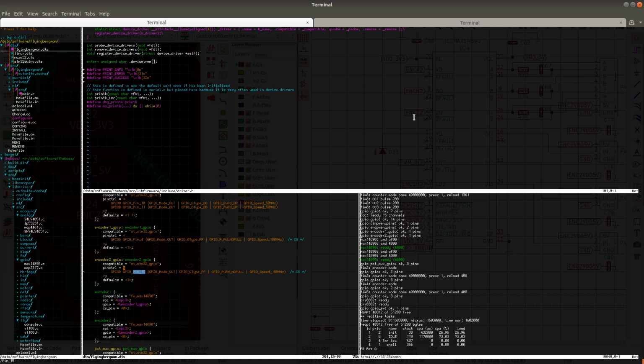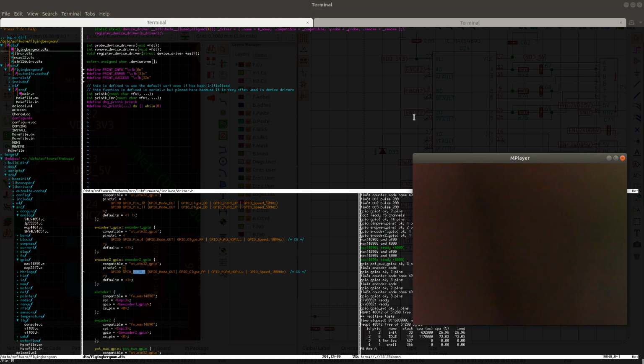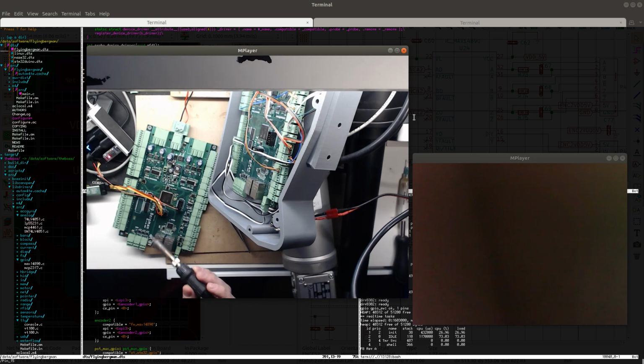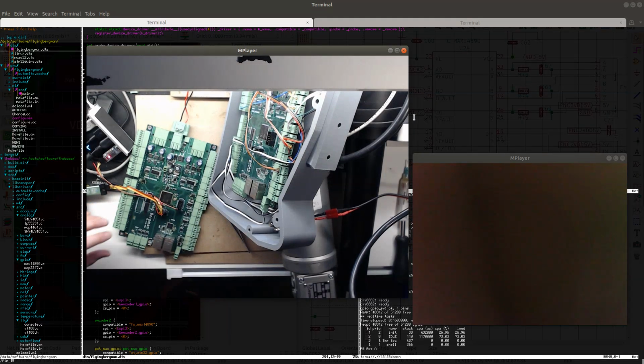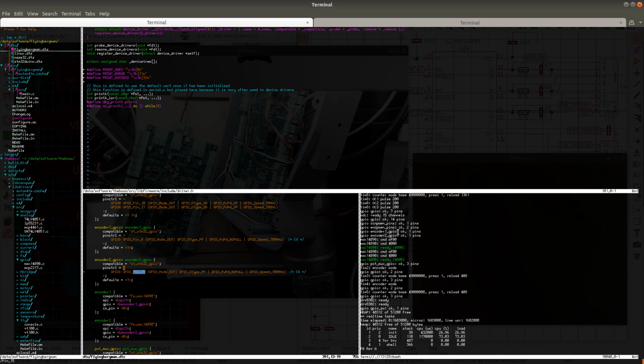I'm going to turn off the board, and I'm going to just grab my soldering iron, the normal one, without using any hot air, and I'm just going to hold it close to that pin to make sure that the pin gets soldered. And hopefully I should be able to start the board and get both chips working. The SPI pin places this particular chip into SPI mode, otherwise it's parallel mode. So it's pretty important to have the SPI pin working. Nope, not yet. Let's see.